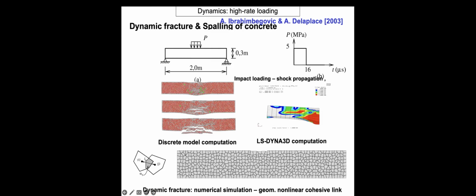You can have a part of the structure with a certain mass and velocity flying off, and you can still hit the stuff it's trying to protect, especially if it's explosives. You can start an explosion by basically putting a projectile directly into the explosive. So if you run this simulation by Dyna 3D, which is done for dynamics, with the finite elements, you cannot really represent what happens to this part of the structure that's falling apart, because basically you only get the damage to be maximum. That means this part is completely destroyed, all is red, and then this means it is eliminated and destroyed. But you don't know how big it is and where it is going to go.